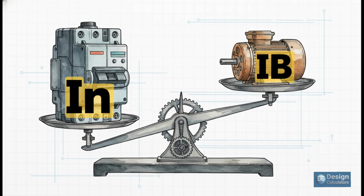And at the heart of all IEC sizing is this one super simple but absolutely crucial principle. The nominal current of your breaker, we call that In, has to be greater than the design current of your load, which for us is the motor, and we call that IB. That's it. This is the starting point for everything that follows.